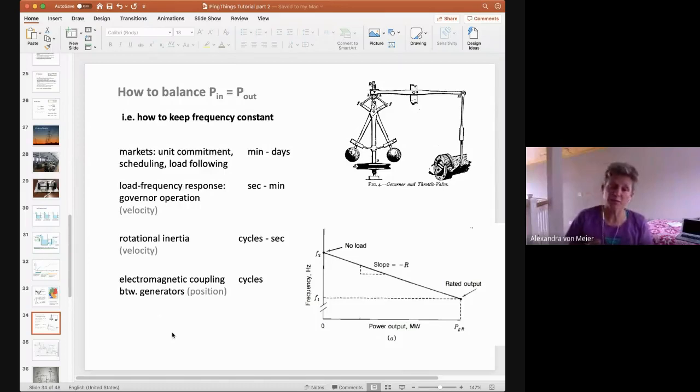And that's basically responsible for the fact that if one generator tries to advance its voltage phase angle, it's going to have to push a little bit harder. It's just like that rubber shaft. If you were going to push harder, your angle would be a little forward relative to the other rotating things that you're driving. So that, instead of being mediated by the material stiffness in the rubber, here it's mediated by electromagnetic forces on the generator rotor, which are not obvious. They're like three-dimensional, super hard to visualize, but it works, and we can come back to that.